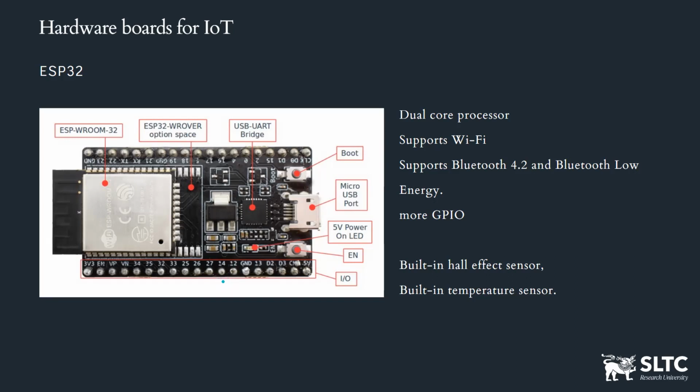For smart automation at homes and in our day-to-day life, we can use these boards, ESP32 and the other boards that I'm mentioning today. But in industry, I think we have much more advanced microcontroller boards for large scale data collection and transferring. So depending on the application, the controller boards need to be selected.